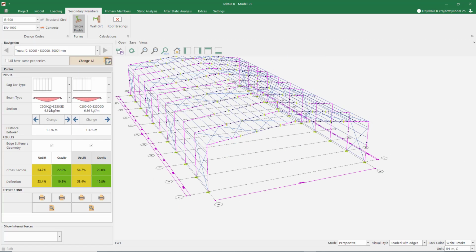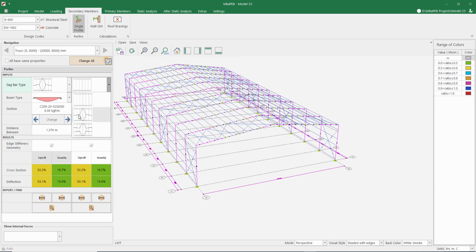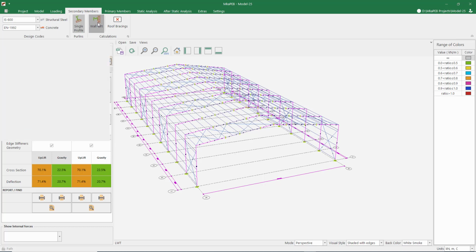When cold-formed steel elements are used as roof purlins, the program uses EN 1993-1-3 as the design standard. From this section, we can define sag rods for roof purlins. We can make purlins simple or continuous. If we wish to change the purlin sections using these arrows, we can use the same section for both purlins. I chose C200 to 15 purlins. And I use single sag rod.